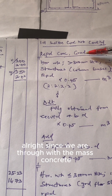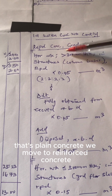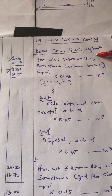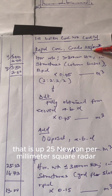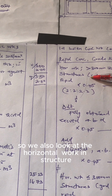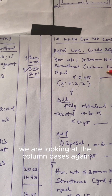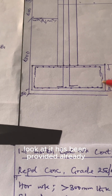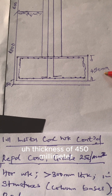All right, since we are through with the mass concrete, that's plain concrete, we move to reinforced concrete, and we have made provision for the grade, which is 25 Newton per millimeter square. We also look at the horizontal work in structure, which is above 300 mm thick. In this case we are looking at the column bases again, the column base footing. Look at it, a thickness of 450 millimeter has been provided already.